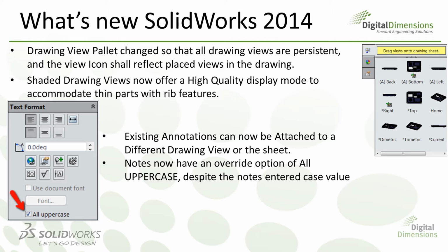In addition to that, we can now set under Tools Options for the document properties, so this would be a template setting, the ability to enforce all uppercase on your notes. This might create an issue such as for millimeters on units, in which case it does also offer an exclusion area that you can type in the items for it to ignore when enforcing this all uppercase rule.